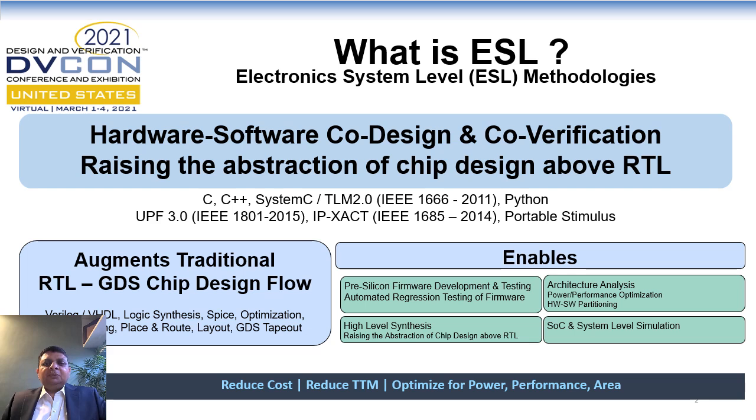ESL is a term which has been used in the industry for a long time in various different contexts. It can be defined as a combination of two broad phenomena. One is designing the complete system, including hardware and software, instead of just focusing on the hardware design. Second is raising the abstraction of chip design above RTL. These are enabled using high-level languages like C, C++, Python, or standards like SystemC, UPF 3.0, IP-XACT, and Portable Stimulus.